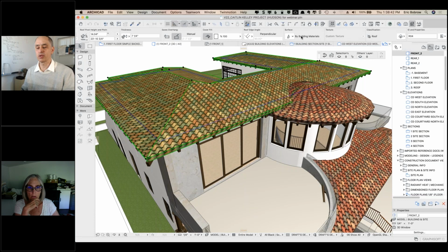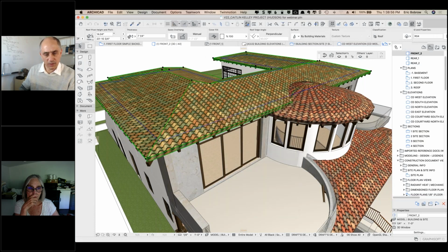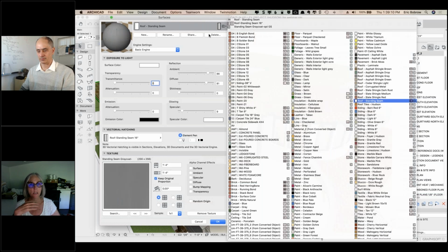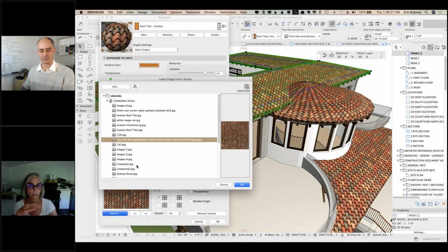So you've got it set to use building materials, which means that if we look at the, okay, this is actually, okay, you've got this particular piece is just the thickness of the roof tile. So the roof tiles, if we go into here. Yeah, that's just a surface. And the reason I did it that way was because I knew that my tile had a certain thickness. And again, this was all to make sure I wasn't exceeding heights. So I put down my underlayments, and I built up the roof the way it would actually be built.